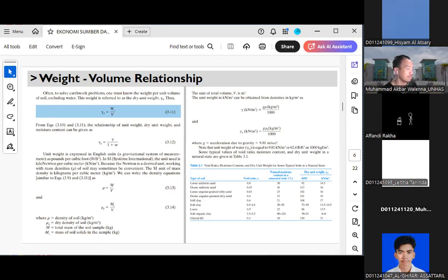Okay, so you definitely need to undertake some degree of soil improvement, or I think you probably need to just change the soils. So we just need to change the several centimeters or meters of this layer of soil into something that is much more competent, much stronger in terms of withstanding the potential loading that it is going to be exposed to. Okay, so that's I think what is important.